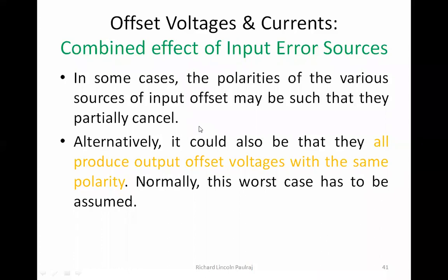This difference is again taken and amplified because the gain is infinity, right? So by having it in the negative feedback mode, I will try to bring down the oscillations. Once the oscillations are down, my outputs are going to be a little more stable compared to the positive feedback.